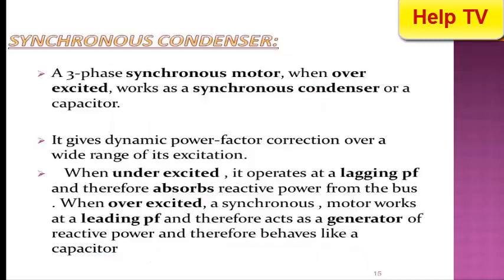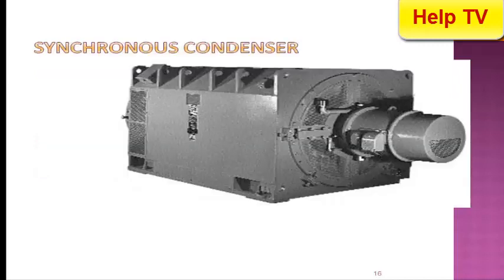Synchronous condenser. A three-phase synchronous motor, when overexcited, works as a synchronous condenser or a capacitor. It gives dynamic power factor correction over a wide range of its excitation. When underexcited, it operates at a lagging PF and therefore absorbs reactive power from the bus. When overexcited, a synchronous motor works at a leading PF and therefore acts as a generator of reactive power and therefore behaves like a capacitor.